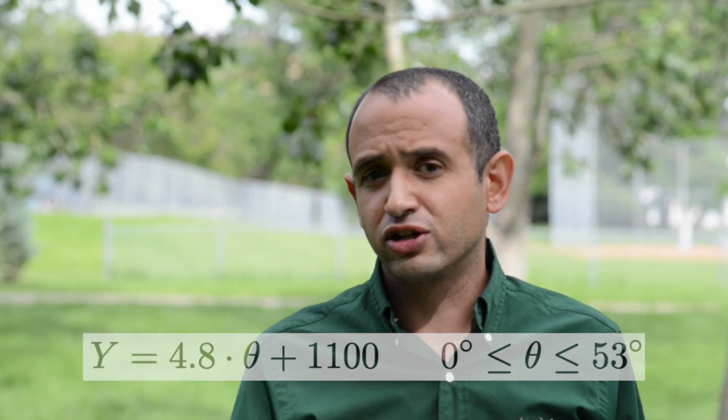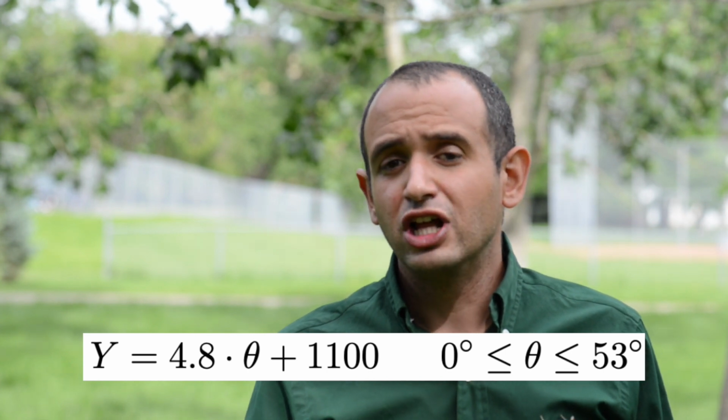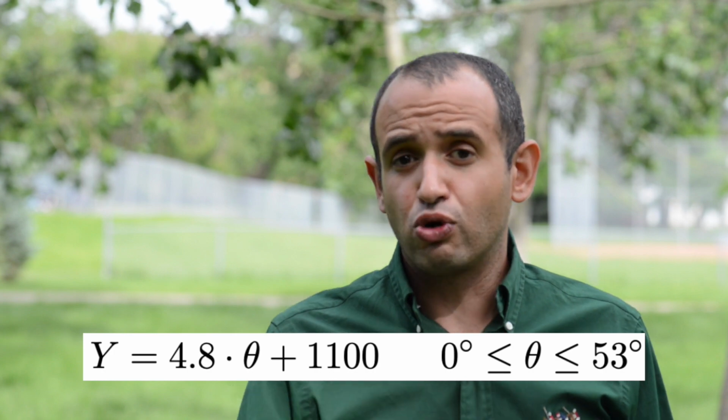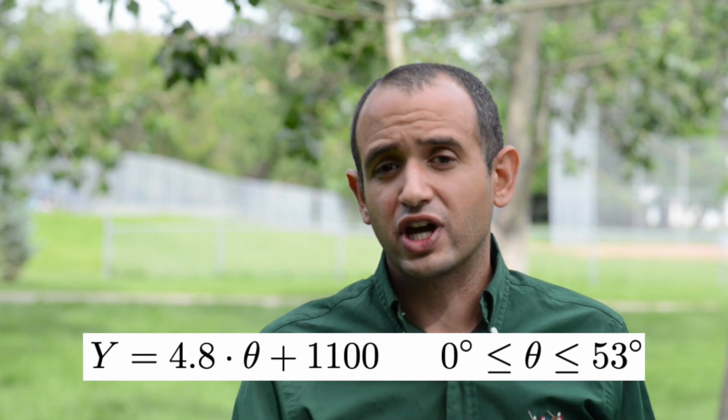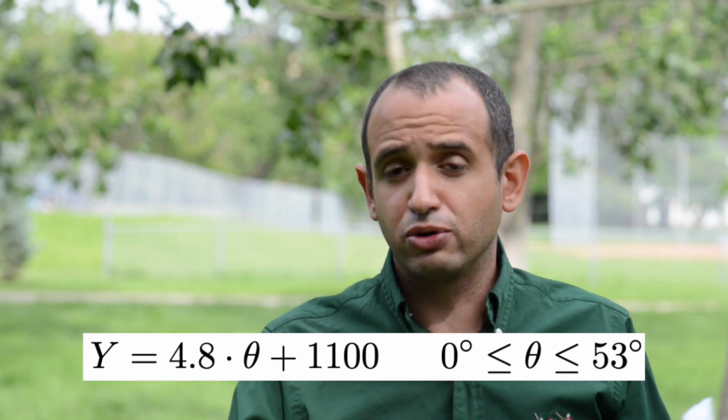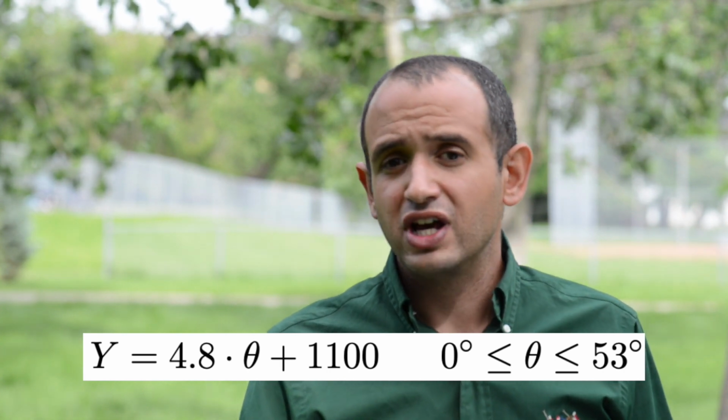The only thing that this model depends on is that there is a global maxima when it comes to tilt. In other words, the optimally producing tilt is above zero and there's only one point. We're not concerned with tilt angles greater than the maximally producing tilt angle because they will produce less energy and use more space than lower tilt angles. So we can rest assured that the feasible space for the tilt angle that we're looking for is somewhere between 0 and that maximally producing tilt angle.